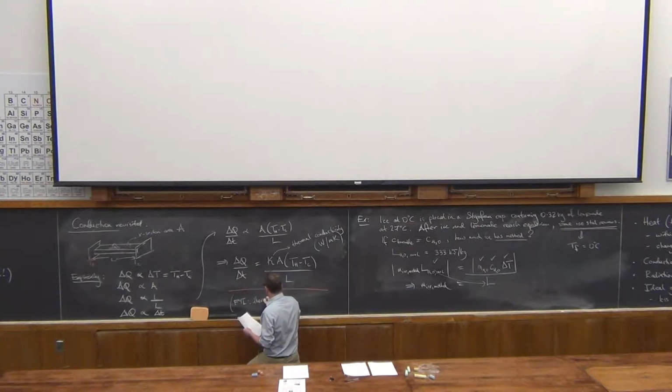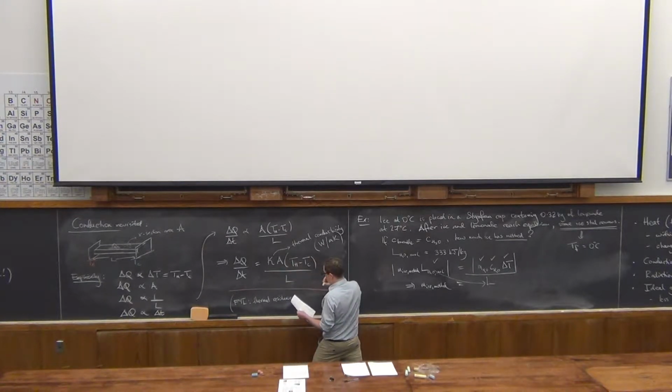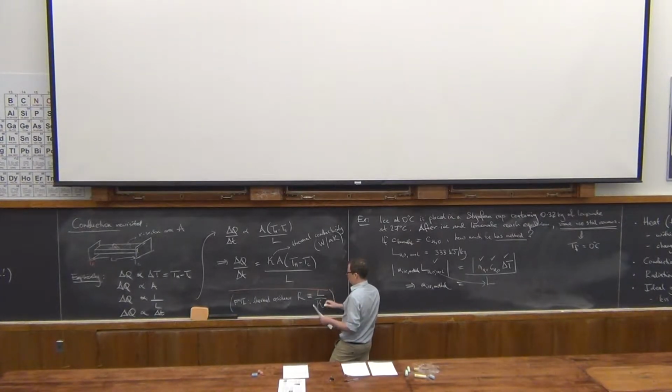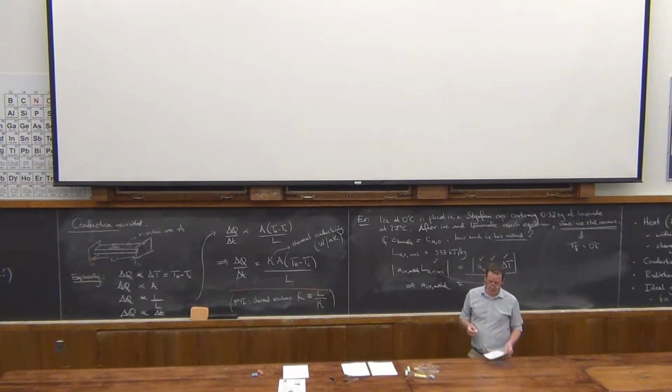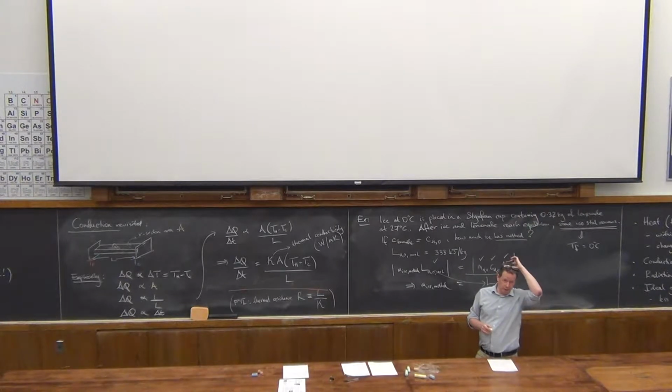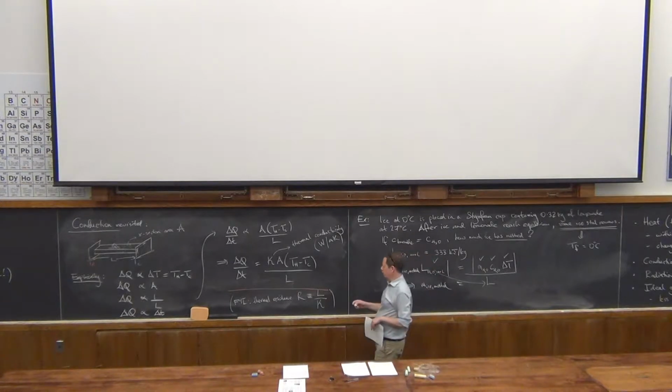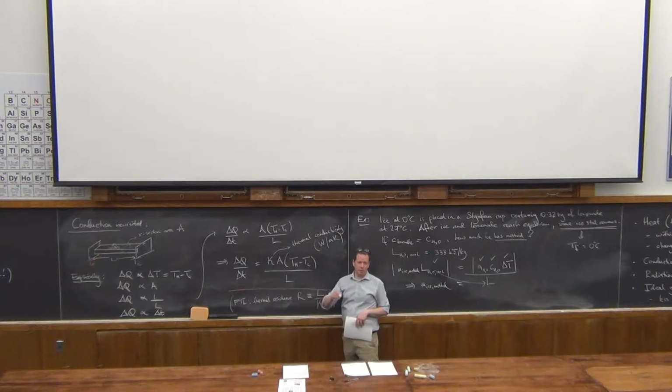The thermal resistance, not surprisingly, this is a conductivity. A resistance is going to be inverse to that. So thermal resistance is defined, triple equality for that, is defined as L over this kappa constant. Any of you who has done anything in homes or construction will often hear about thermal R values in terms of insulations. This is where it's defined. So the thermal resistance is inverse to the thermal conductivity, as you would expect.